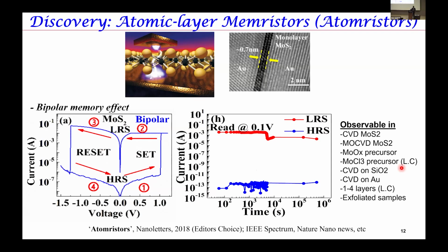In terms of vacancies, of course, at the device level, you have a concentration of vacancies, maybe 10 to the 11 or 10 to the 10 per centimeter squared. How many vacancies are filled depends on the compliance current. If you see this IV curve, this current here is flat. It's not flat because it wants to be flat. We set it to be that way to prevent the device from damage.